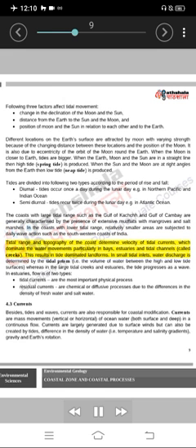Tidal range and topography of the coast determine velocity of tidal currents, which dominate the water movements particularly in bays, estuaries and tidal channels called creeks. This results in tide-dominated landforms. In small tidal inlets, water discharge is determined by the tidal prism, i.e. the volume of water between the high and low tide surfaces, whereas in the large tidal creeks and estuaries, the tide progresses as a wave.